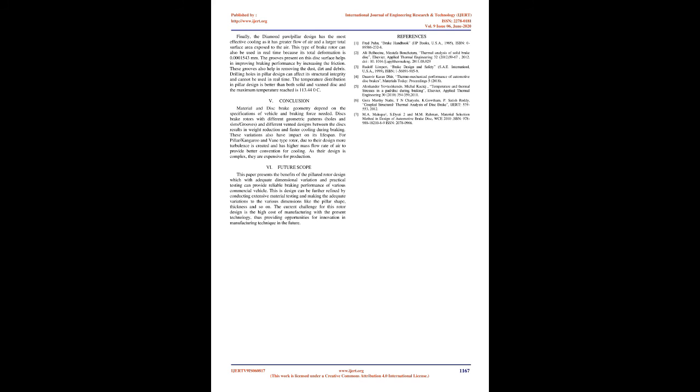6. Future scope. This paper presents the benefits of the pillared rotor design, which with adequate dimensional variation and practical testing can provide reliable braking performance for various commercial vehicles. This design can be further refined by conducting extensive material testing and making adequate variations to various dimensions like the pillar shape, thickness, and so on. The current challenge for this rotor design is the high cost of manufacturing with the present technology, thus providing opportunities for innovation in manufacturing techniques in the future.